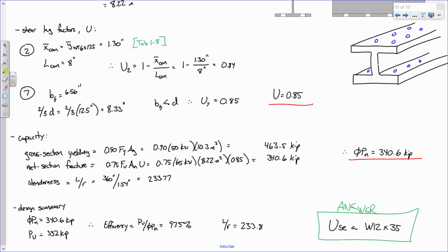They are starting to catch on with the bridge construction industry. You are correct that it is a newer innovation. We're probably going to have different maintenance challenges with integral abutments down the line because they're so new. You don't have a large population of 60-year-old bridges with integral abutments to say, okay, now we know what's going to happen to them. So I'm sure there will be maintenance challenges down the line, but right now, are they better than regular old expansion joints? Yes.